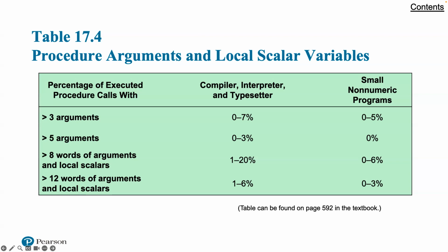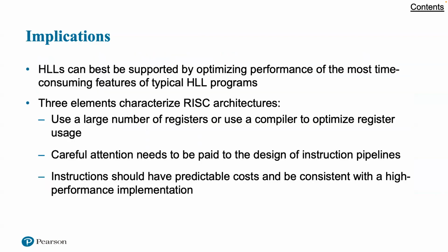These results reinforce the conclusion that operand references are highly localized. A number of groups have looked at results such as those just reported and have concluded that the attempt to make the instruction set architecture close to high-level languages is not the most effective design strategy. Rather, high-level languages can best be supported by optimized performance of the most time-consuming features of typical high-level language programs.